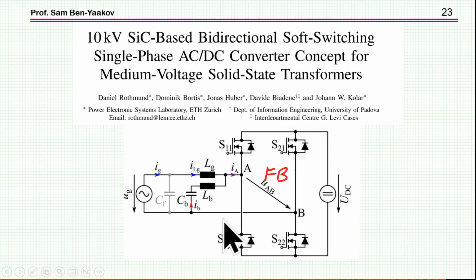And this is a rectifier again, power factor corrected. Here they're using a full bridge. In the case of a full bridge, you do not need a rectifier because a full bridge can accommodate both positive and negative voltages. Here we see the main inductor, and here is the auxiliary inductor plus capacitor, which is a little bit problematic because this capacitor has to, of course, carry the ripple current, so it's not a little capacitor, it's a pretty hefty capacitor. So this is one approach.